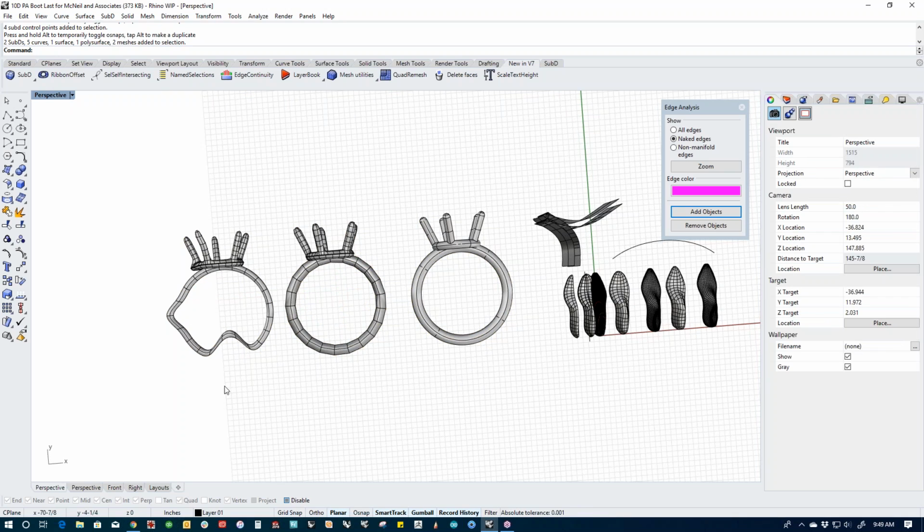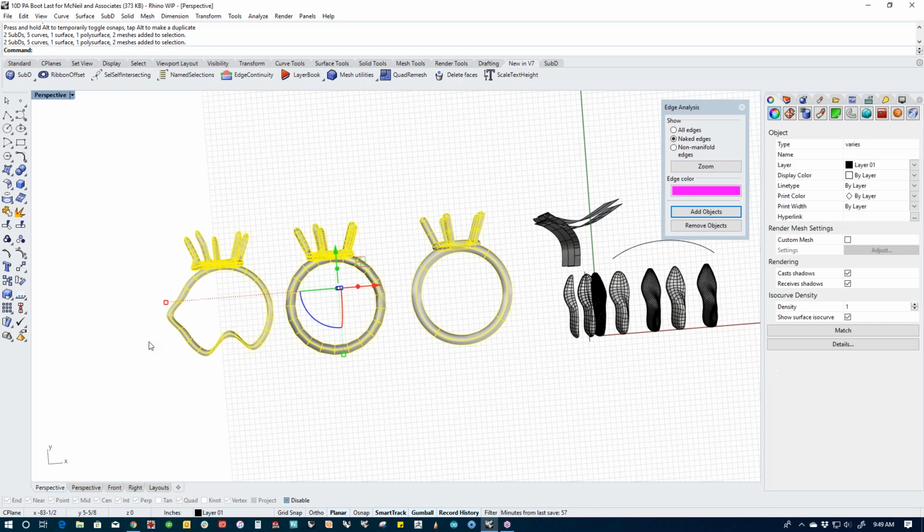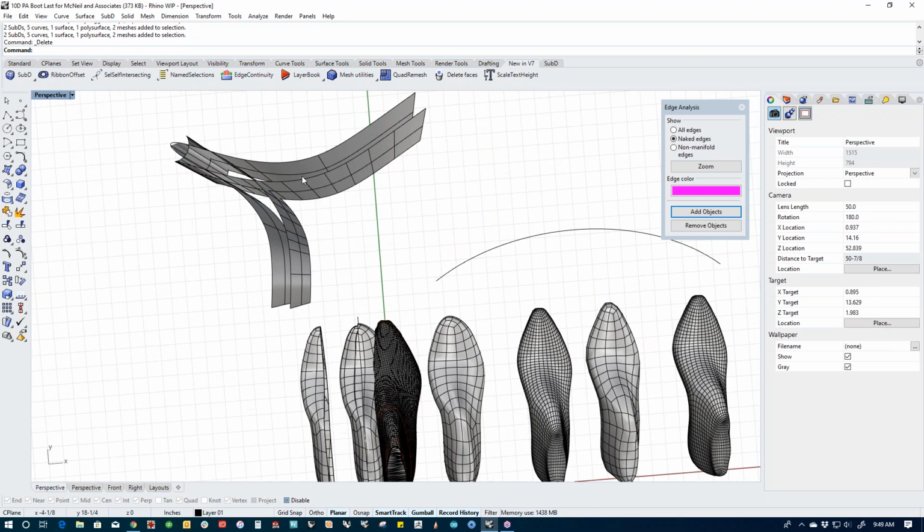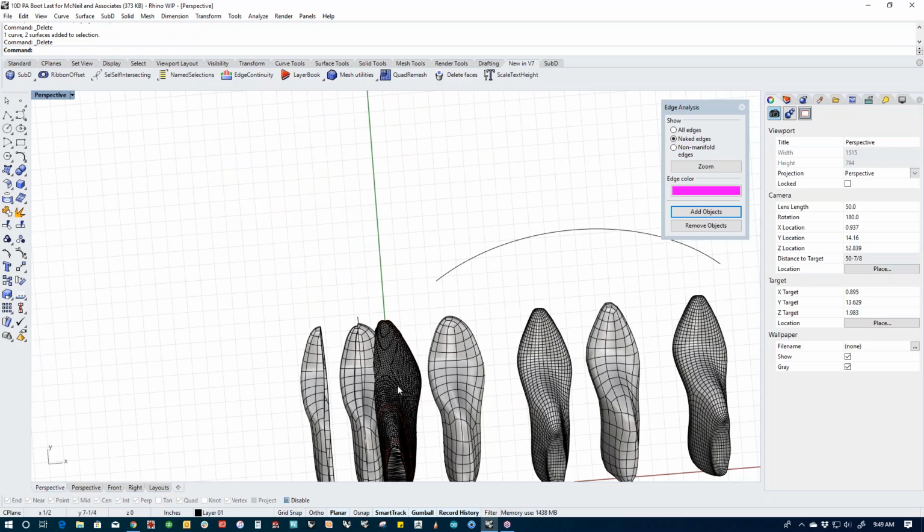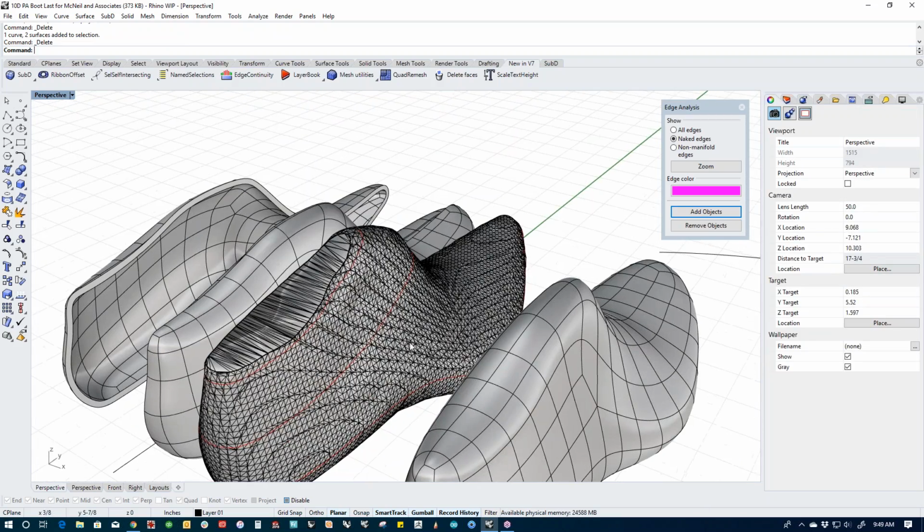Instead of cranking the whole thing into one big fat SubD, you might want to break it up into a couple little pieces. But in this case down here, this actually is a super successful way of doing this, where in the past you would have had to try and project curves and draw surfaces and loft it and all that kind of stuff. And at the end, you'd still end up with a poly surface that would be difficult to deal with. Okay?